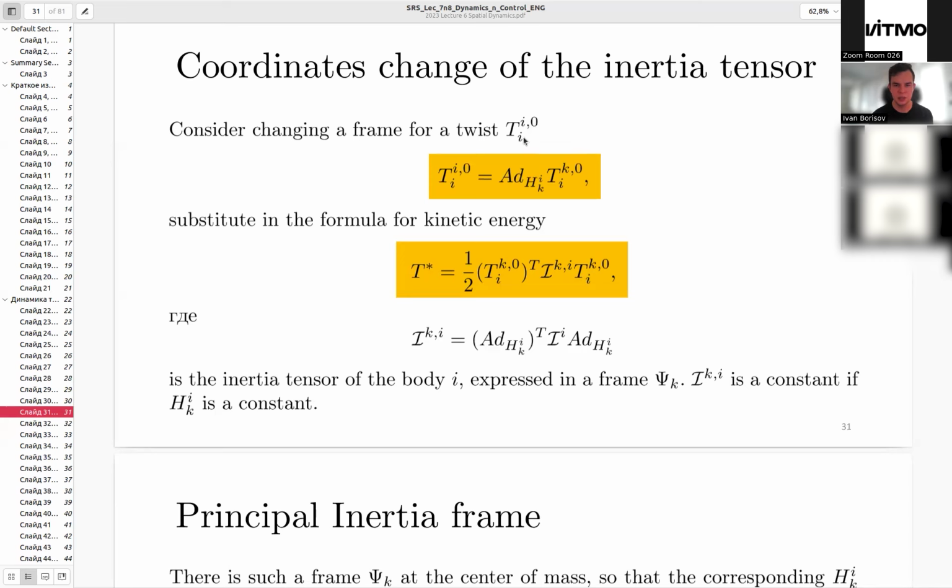If you have initially a motion for K, you can change the frame such that the same motion will be represented according to the frame I. Then we just need a joint matrix multiplication such that the same motion of a body I that moves with respect to body 0 will be expressed not in K but in I.